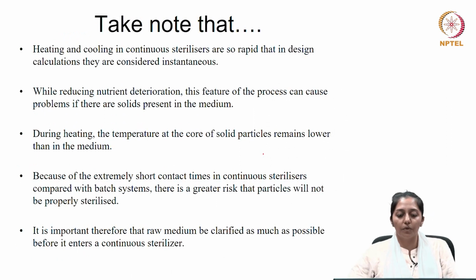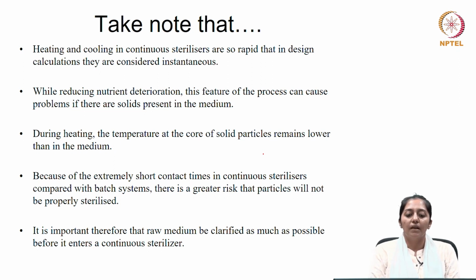So what is to be noted here is that heating and cooling in continuous sterilizers are so rapid that in design calculations they are considered instantaneous. So while reducing nutrient deterioration, this feature of the process can cause problems if there are solids present in the medium.